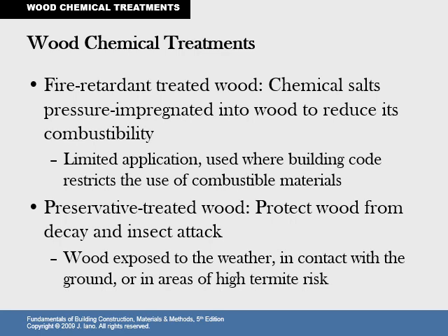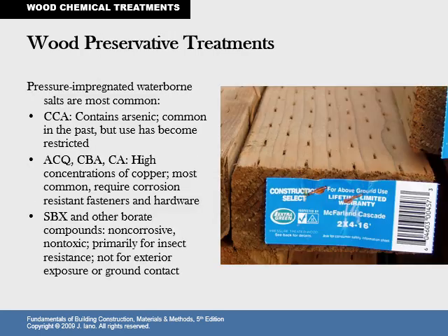There's preservative treated wood, sometimes green wood. You'll see a wood that may be green, not necessarily green in that it's fresh, but it may be coated. It protects the wood from decay or insect attack. Especially here in Florida, wood exposed to the weather and in contact with the ground or areas of high termite risk. Especially on your sill plate, it's a good use for it. And also on your decks.